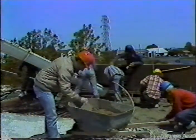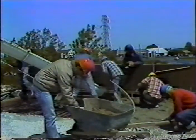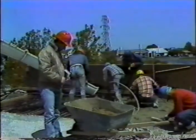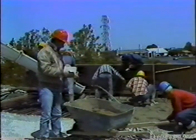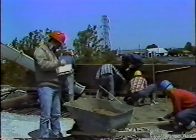Checking the concrete temperature is simple. Just insert an approved thermometer into the sample, wait 10 or 15 seconds, and read it. Record the temperature on the delivery slip. That's all there is to it.